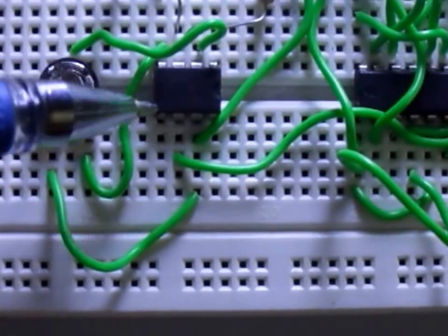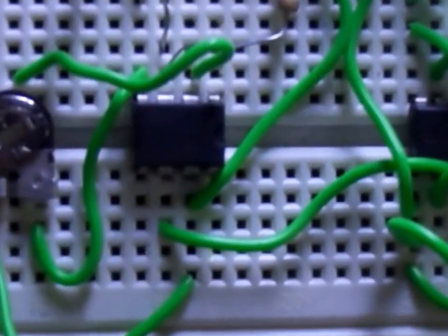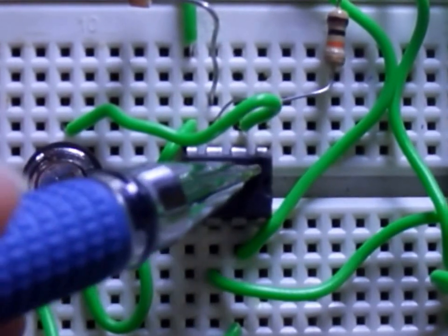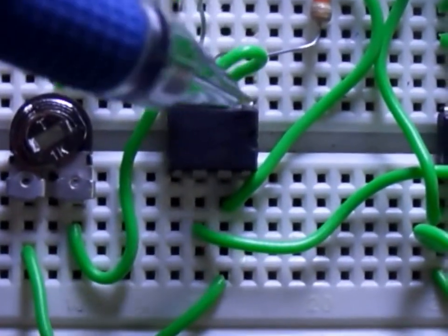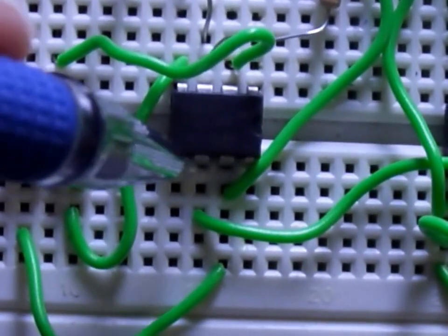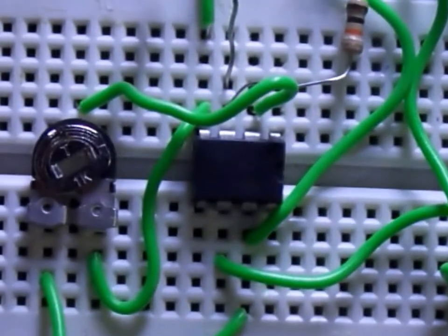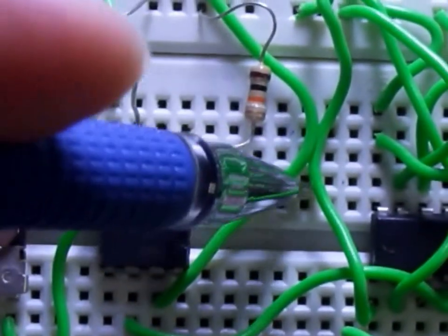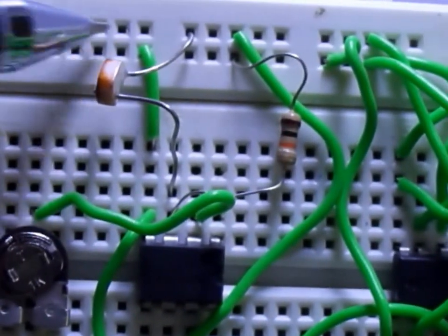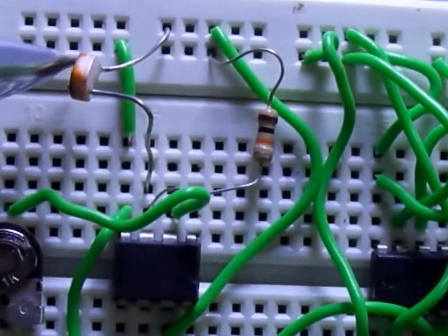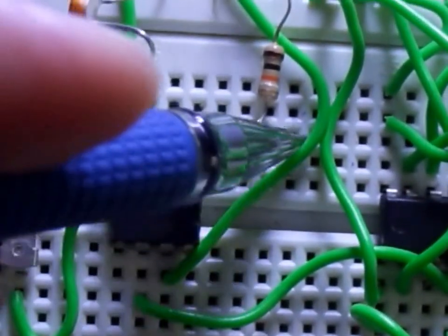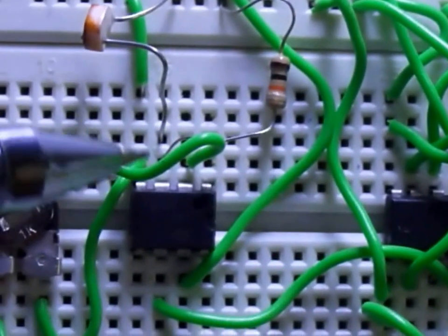So this is the first part, that is IC741, and you see a notch here, and the counting of pins starts from here. That is, pin number 1 is here, pin number 4 is this, then pin 5, 6, 7 and 8. So I have connected this wire. You can see this is towards the positive terminal. I have taken this one as the positive line and the lower one as the ground line. So this is pin number 7 and this is connected to the positive terminal